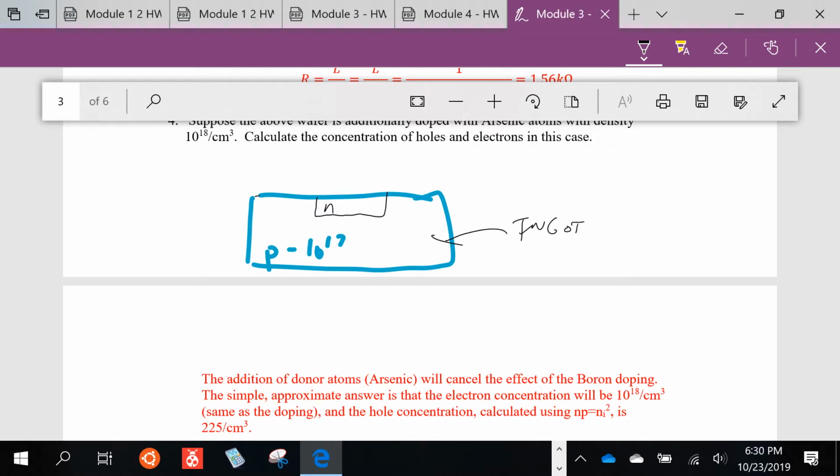And when we want to make the diode, we use another process where we diffuse materials in there. We'll put this in a chamber that has arsenic ions or other column 5 elements, and we'll block off certain regions. Don't worry about the details of this yet, but we block off certain regions so that the gas molecules can only diffuse into certain regions of the wafer.